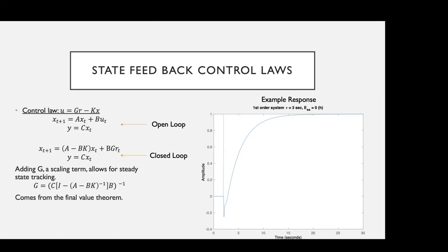Well, if you assume a first order system, you don't have any jitter. It just goes to it. No, that's theoretically right, but if you have a real control system, there's going to be electronic noise, your sensor's going to have noise, that kind of thing. Yeah, I'm not sure. Probably not a lot, but probably just a low pass filter, a time average. But that's what the Kalman filter is. A Kalman filter is just smoothing. Basically it's doing something intelligent with a batch of data and coming up with a better result, whether it's time averaging or something else.